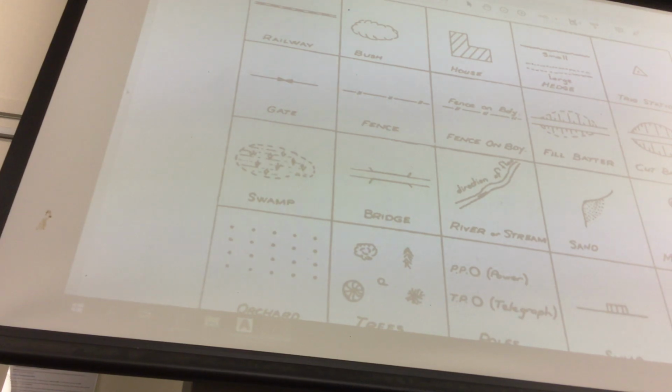There will be a lid of some sort, which it's a little bit out of perspective. I'll try and draw it a bit better. The man goes down. That is 600, and the diameter of this is 1050. That's a standard manhole.